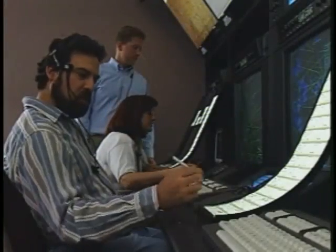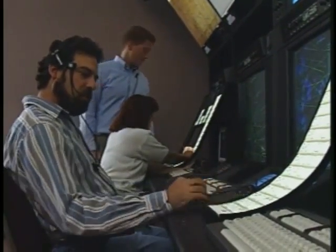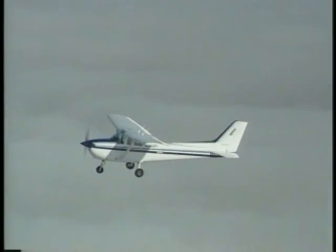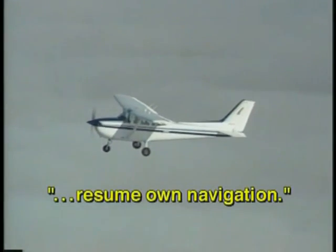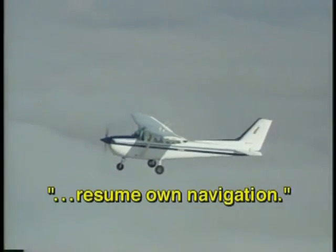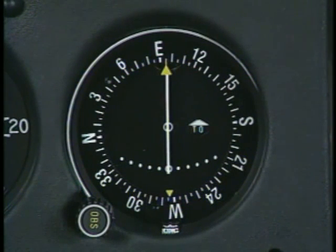Departure control will then give you specific headings to fly in order to intercept your clearance route. Once the final vector has been given, the controller will tell you to resume own navigation. This phrase means that the controller now expects you to navigate using your own equipment. It does not mean that your flight is no longer in radar contact.